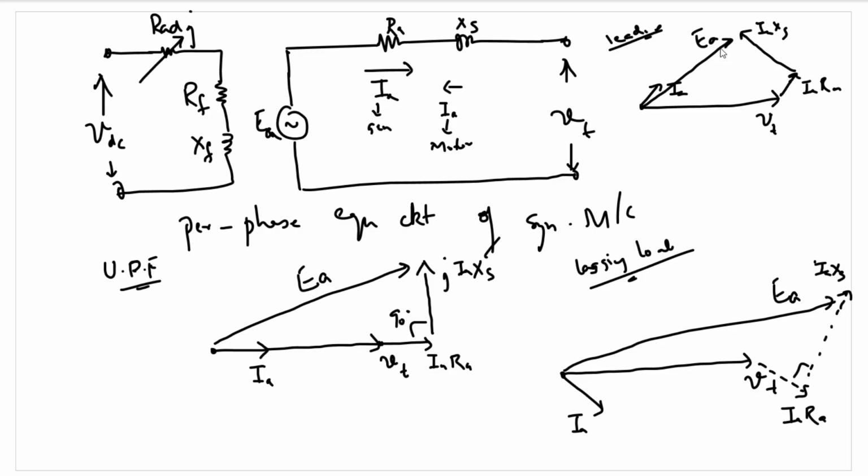In the equivalent circuit, the rotor side is simple. It only has a resistance and an inductance of its own, and we can externally use a resistance to change the magnitude of current IF in this circuit. That will actually change the amplitude of this induced EMF.